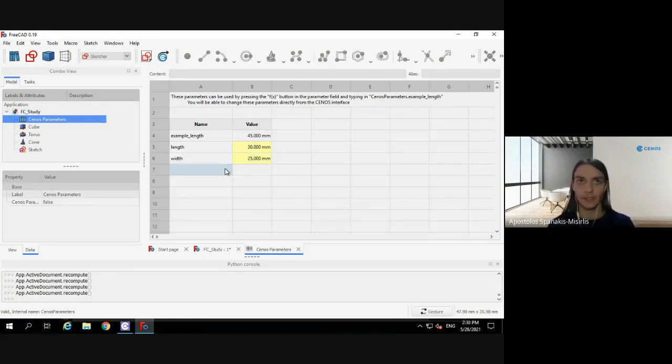It's a table basically. And I've simply entered the width and length of some parameters, and I've assigned the corresponding value. And of course, if you have more shapes, for example, the thickness of a wire, you could also add an extra parameter. So for example, thickness, let's say I want this to be 5 millimeters. So I've added 3 parameters here.